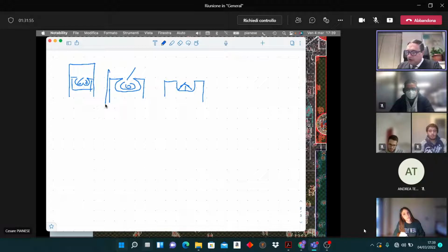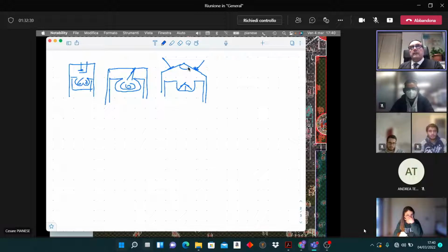And then the shape of the head, the combustion chamber, could be something like that, or where you are going to put the spark plug, if it is an SI spark ignition engine, or where to put the injector, or what should be the angle of this head, or whatever kind of things.